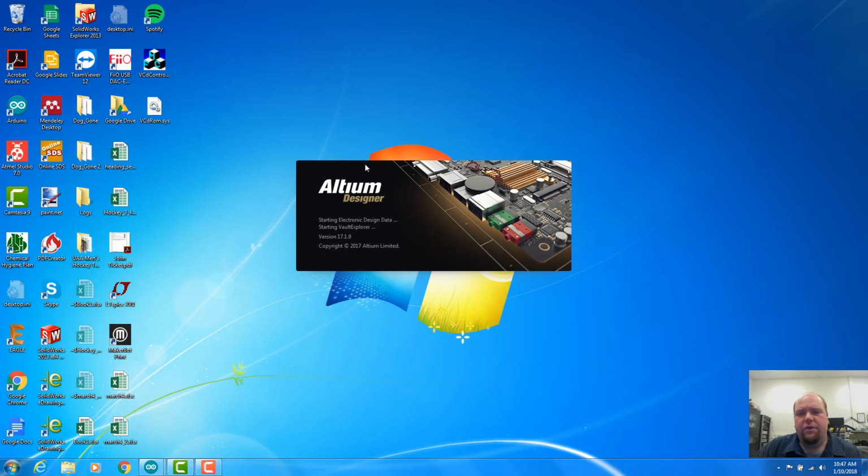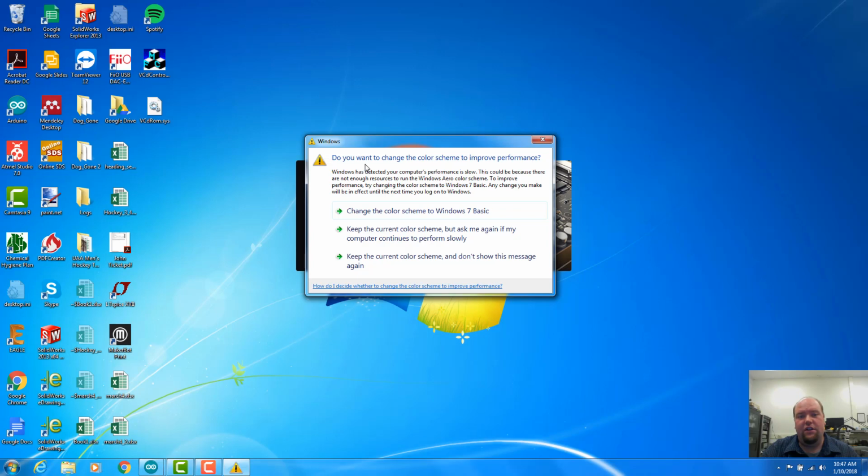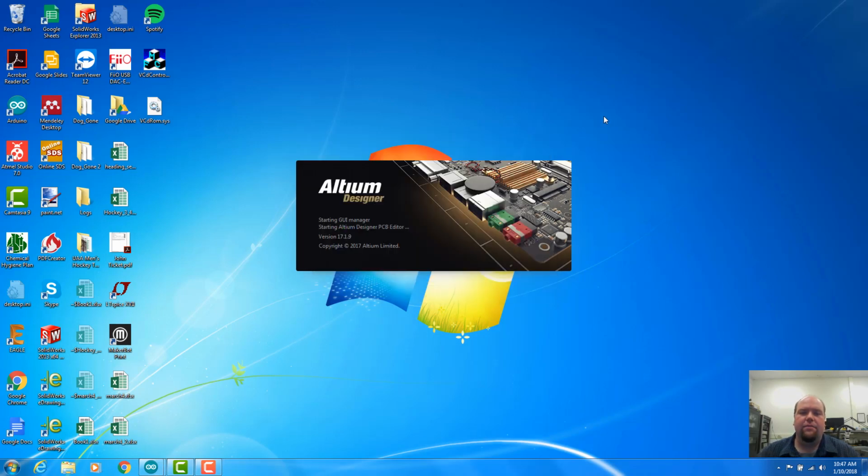And the first thing we're doing is we're going to be creating a part. And it's important to understand that with every component, there's basically two halves to each component. There's the schematic side. The schematic side shows logically what signals are connected to what pins, right? What signals are represented by the part, what inputs and outputs the part has. And then there's the footprint side. And the footprint is the physical details of the part. So the physical details of the part, like how big the pins are, how big the footprints need to be, the physical size of the part, the physical orientation of each of those pins.